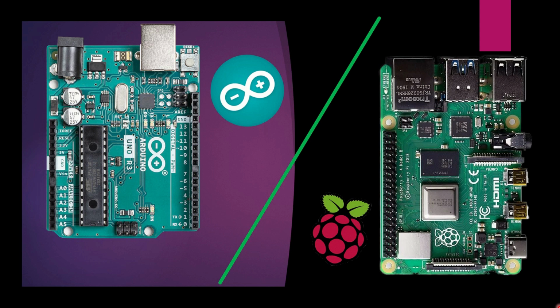Here, by real-time control, I mean, let's say there is a requirement to send a signal to an external peripheral at certain intervals. The Arduino, since it's running a single program, will make sure that signal is sent almost exactly after that time interval, repeatedly. But in Raspberry Pi, this task will be given to a scheduler, which will try its best to execute this command of sending the signal, but it's not a guarantee. So basically, it's better to use Arduino whenever we need to work with a hardware component.